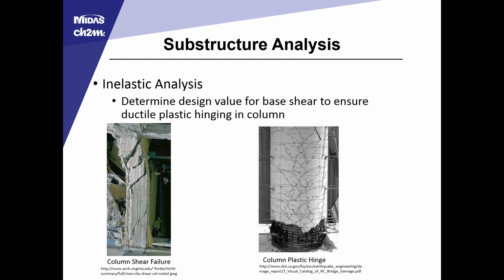So moving into the inelastic analysis, the purpose is to force a plastic moment failure before a shear failure. The image on the left shows a shear failure, which is undesirable and would almost certainly end up in a superstructure collapse. On the right, we have a column plastic hinge, and while that column likely has no shear capacity left, it still is stable and able to support the superstructure above.